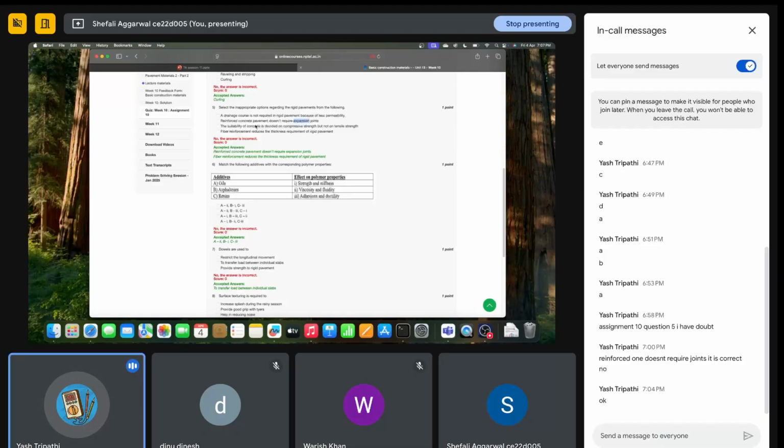And when will we provide the dowel joint? When we are not providing complete reinforced... sorry. Oh okay. Okay, in the slide it was told that in complete RC pavements we are not providing expansion joints, and in case of only concrete pavements we will provide expansion joints and dowel bars. Okay, so the statement is wrong. Fine. Okay, I will talk to these people at NPTEL.